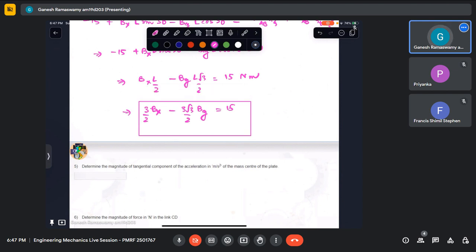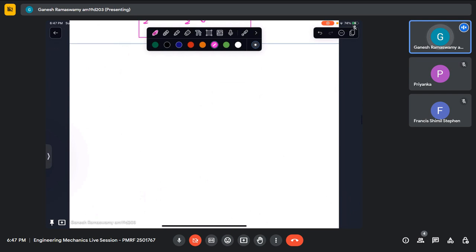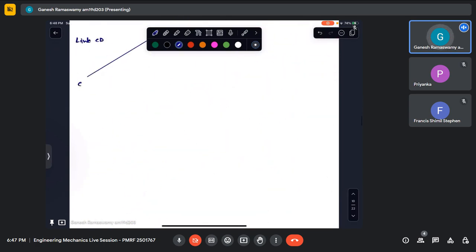Very well. Now let us analyze the free body diagram for the third link, which we have not touched till now. The third link is link CD. This is C, this is D, I think. Similarly, at C, I am at liberty to put my reaction directions. Let me call this Cy, and this Cx.